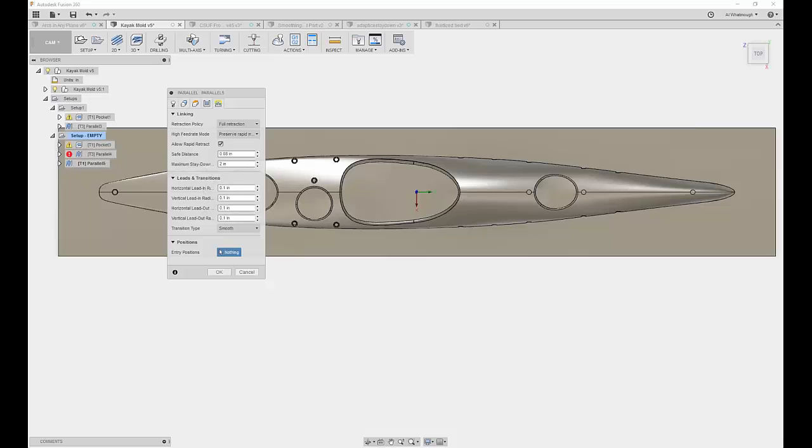And chiming in also, changing your clearance heights and your retract heights also helps a lot because, like on my smaller machine, the Pocket NC, the default's pretty tall relative to the amount of space I have. So moving that down for me gives me a lot more speed overall.